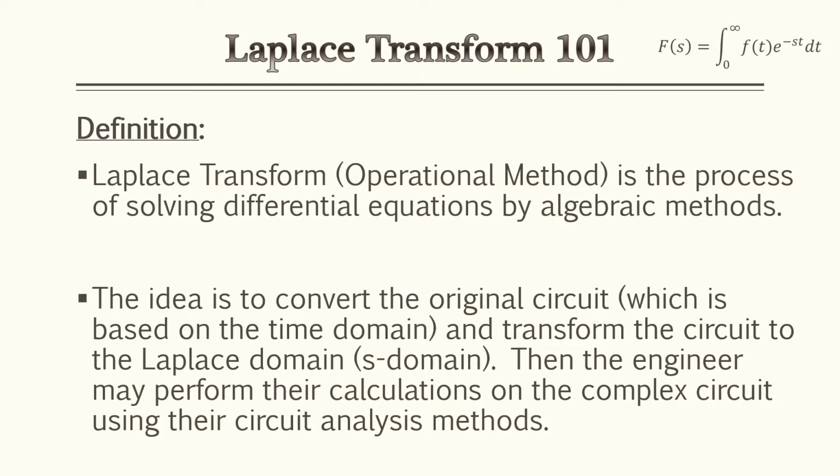Well, electrical engineers use it to convert original circuits, which are based on the time domain, and transform the circuit to the S domain or the Laplace transform domain. Now, once they do that, they can use algebraic methods, manipulate the equations, and then revert back to the time domain to solve whatever calculations we want to perform on that circuit.